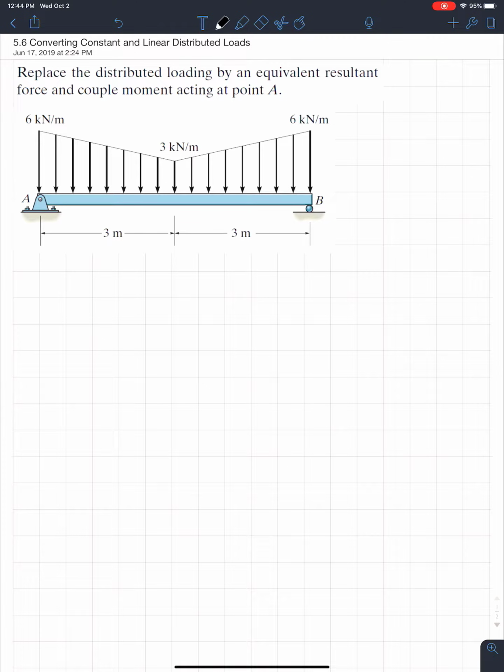However, if we just treat the loads as that pressure and not a single force, it's very hard to determine things such as resultant moment. And the reason for this is when you're dealing with a moment, you have to have a distance. And if that force doesn't act at a specific point, but is rather spread throughout, let's say, a beam, it's very hard to find that moment arm. So the last part of this week is we're just going to look at distributed loads.